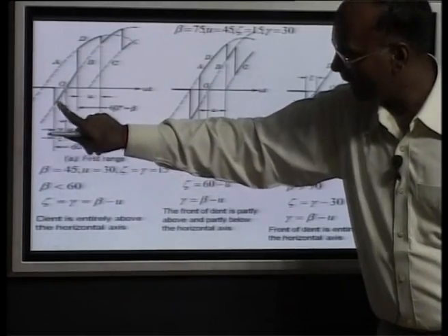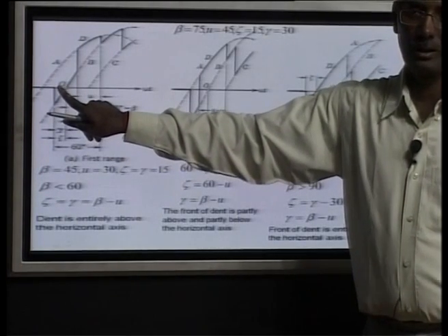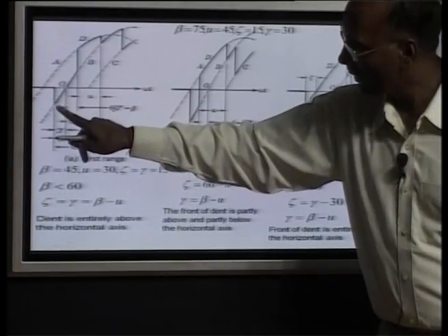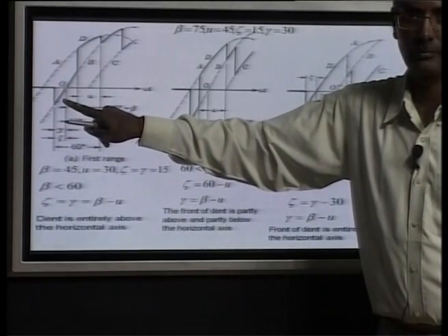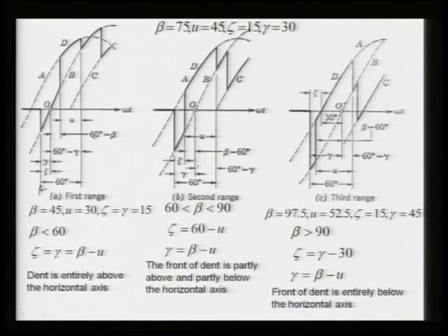It was conducting up to here, means there was a commutation between 3 and 5, and it is over. Now, here 4 and 5 are conducting, and this will go up to here when 6 is being fired.